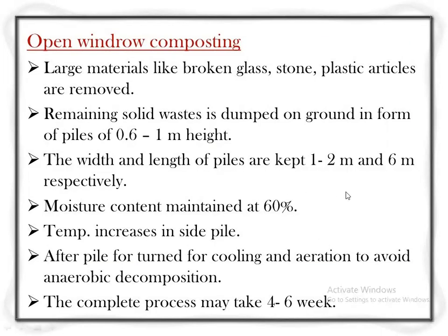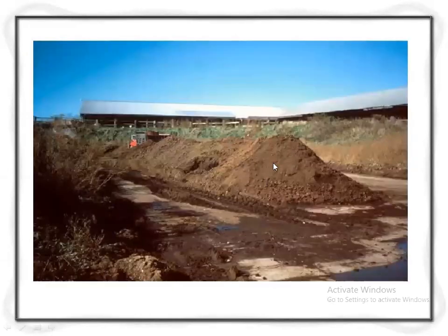And the moisture content is maintained at 60%. Temperature is increased in the side pile, and it is allowed to cool and aerated to avoid anaerobic decomposition. This process may take 4 to 6 weeks, or 2 to 3 months are required for the composting of this organic waste.